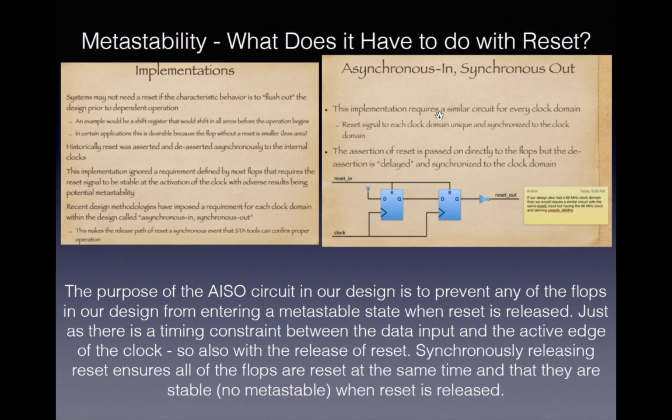But for us, in our classes, we will always use reset. The problem historically was that the release of reset was controlled by a manual switch or an RC circuit on the board that had no timing relationship to the clock inside of the design.